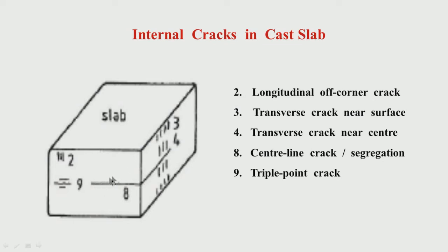So there is solidification shrinkage, and moreover this area has too many segregating elements because of high segregation. It is impure, purity is relatively less here. So this area is relatively weak.